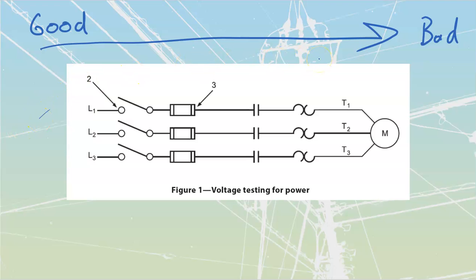I'm going to use a couple of different things to do so. First of all, visual inspection, looking at things and seeing what it appears to be inside there. Is there smoke coming out of it? These are pretty big clues. Is there discoloration? Anything that looks like it has problems, water in it, or looks like it's been recently disturbed, destroyed, or tampered with? All of that provides part of our inspection. The rest is done with circuit testing, because we can't actually inspect electricity. We can't see it. We have to do that through test and instrument measurements.